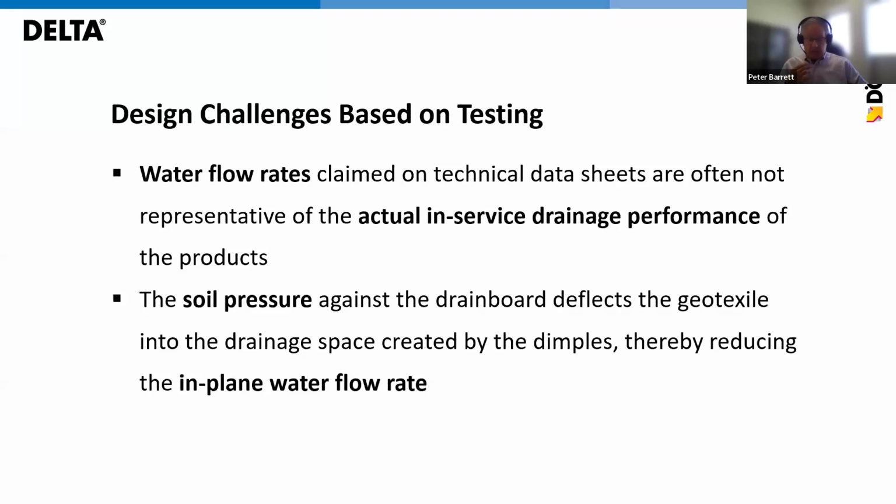There are several specific challenging soil conditions which elevate both on and off-site risks associated with groundwater and stormwater management. Sensitive or collapsible soils can behave unpredictably when water is introduced, and this can negatively affect bearing conditions for proximate buildings. Swelling and shrinking clay are soils that can be subjected to significant volumetric change associated with the amount of water present in the soil. Organic soils, including peat, are generally weak and can deform excessively when subject to new loads.